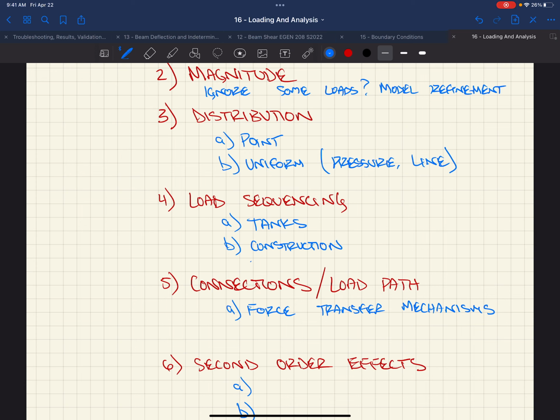That rebar is going to transfer vertical forces, and it's also gonna keep the slabs from pulling apart. Well, in some cases, we might wanna just put a smooth dowel, like a 1-inch square solid stock or 1-inch round stock, and then actually have the contractor grease one end of this when they put it in the slab, so that the slab can move around. So we're not restraining these cracks, but it allows this thing to transfer up and down. So you gotta think about force transfer and connections and load path and how we're allowing things to move and transfer from one thing to the next.